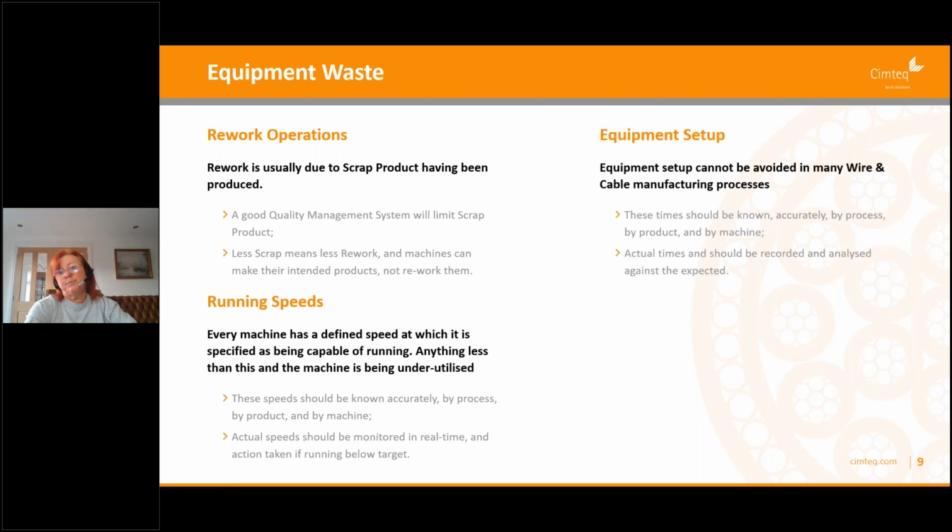So, setup. Again, we can't avoid setup. That's the nature of the game, but we need to have a very precise view of what those times should be, and be quite strict on recording them and comparing the actual times to the ones that we've spec'd. When they differ, we need to do something about it. It's a case of designing the process, knowing what the setup times are, and then comparing the actuals.